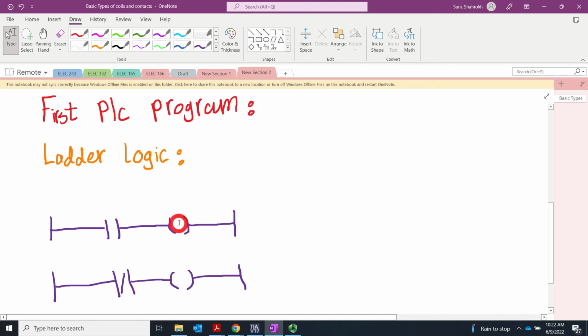So as you can see here, this coil is on the right side. And as I mentioned before, usually the power flows from left to right. You could extend your ladder logic, so that means somehow I could connect these two, but I didn't do that here. We are going to separately run these two ladder logics in our Siemens PLC, but technically you could actually do that too if you want.